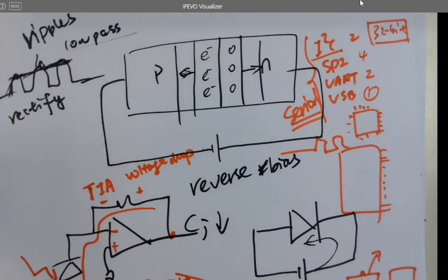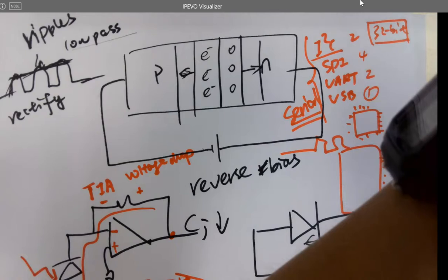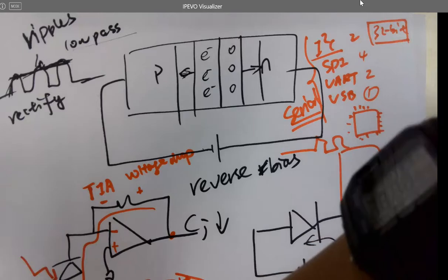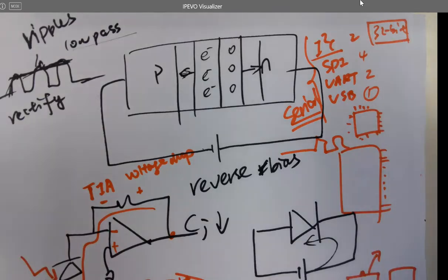No, you still need digital chips and serial communication. It just speeds up the clock. And sometimes you have a pretty large technology like 500 nanometer, because of these transistors. I know this is bigger than that, but for example, this is a 500 nanometer transistor. So the 2 nanometer transistor right now is going to be how much? Like only this much compared to the 500, right? So you can imagine there will be a lot of capacitance for the bigger size, which means you cannot toggle it really fast. That's why we want to use smaller process sizes, because it's faster. That's why your phones can be a lot faster every couple of years, using 2 nanometer, 5 nanometer technologies, way faster than 500, right?